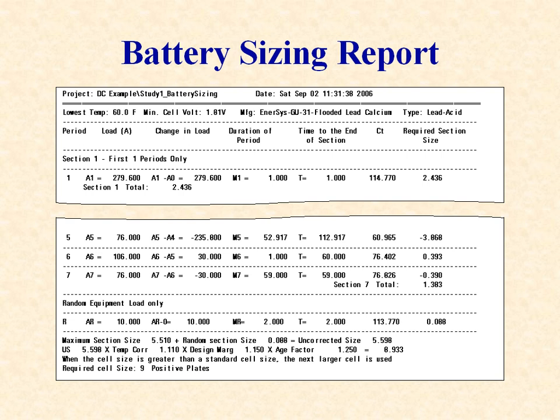The result of a battery sizing study is the battery sizing report. PTW provides reports that match the sizing worksheets defined in IEEE 485 for lead-acid batteries and the worksheet in IEEE 1115 for nickel-cadmium batteries. Shown here is the beginning and end of a typical sizing report for a lead-acid battery. The report for a nickel-cadmium battery is similar, except the size is calculated in ampere hours rather than in positive plates. For a lead-acid battery, as shown, the required number of positive plates is calculated for each time period.